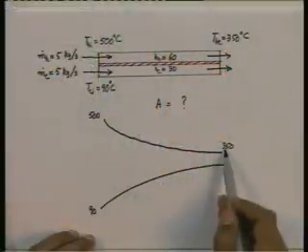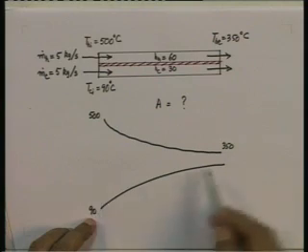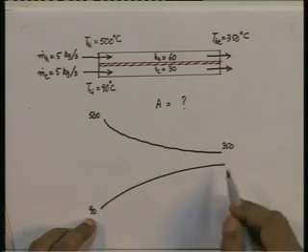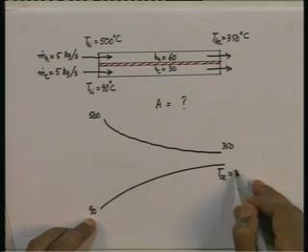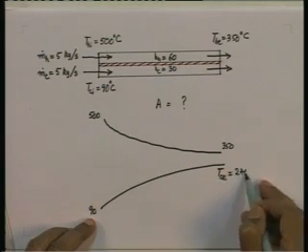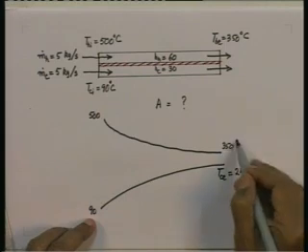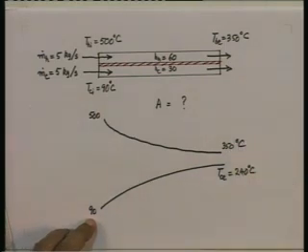So, the change of temperature on the hot side is 150. So, it follows that the change of temperature on the cold side must also be 150. So, TCE must be equal to 240, that follows. I do not have to even do any real calculation for that.